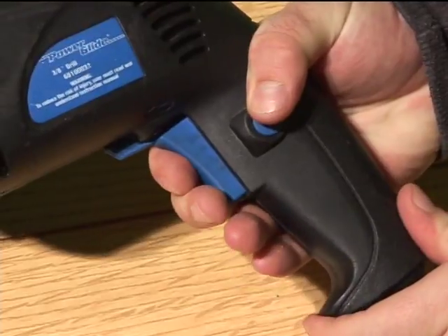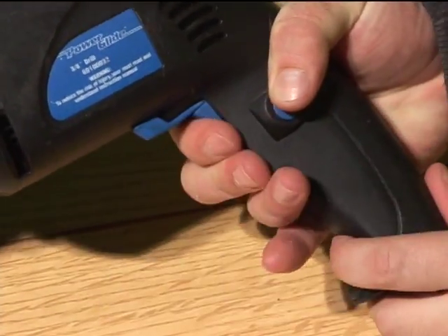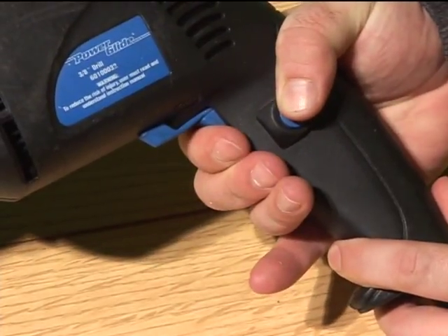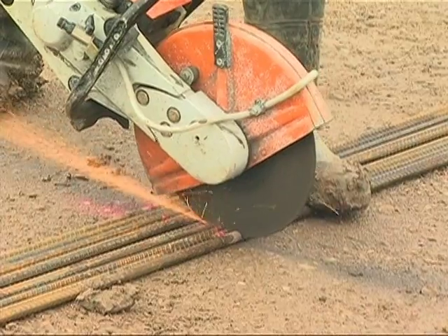Handheld portable power tools are to be equipped with a constant pressure switch or control that shuts off the power, thereby stopping the tool when pressure is released. Many older portable tools do not have this feature and should not be used.